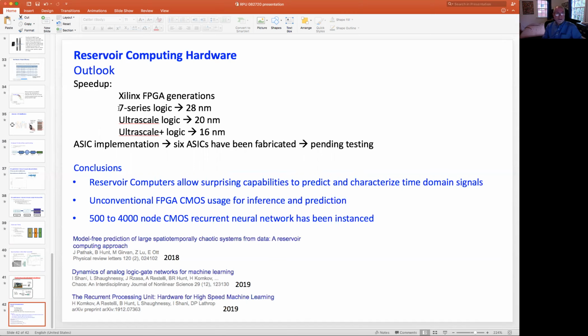The ASIC implementation is something that we look forward to for removing some of the limitations that the FPGA places. That is, the input data and the output data on FPGAs always come in strictly binarized, where the reservoirs could in principle take non-binary input, like direct RF input into a circuit. So that's something that we should be able to try by feeding things like RF signals or even chaotic signals directly into an ASIC for machine learning tasks.